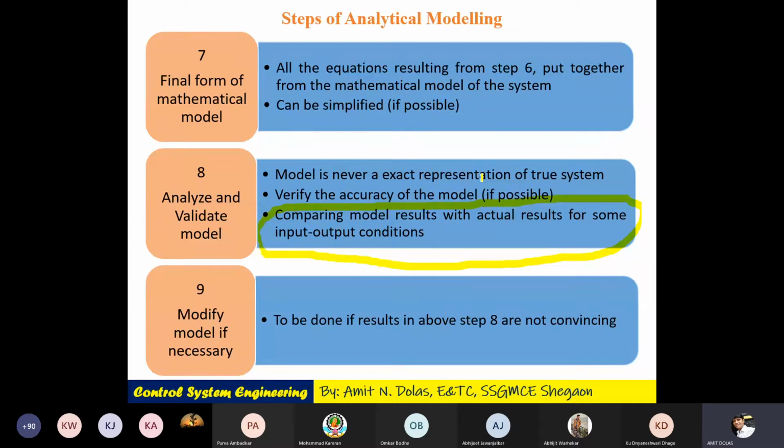Say I have a resistance of 1K and I'm validating that. I apply 1 volt, then I am expecting 1 milliampere current. I apply 2 volt, I'm expecting 2 milliampere current. But think of the temperature. I'm doing this experiment at room, ambient temperature, and the readings are 1 milliampere, 2 milliampere, likewise. But if I increase the temperature to say 50 or 55 degrees centigrade and perform the similar experiment, your readings may somewhat deviate.